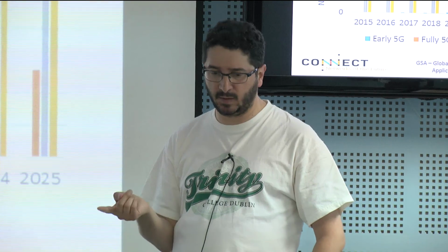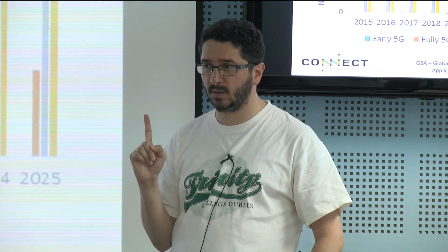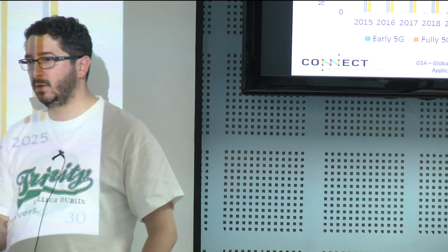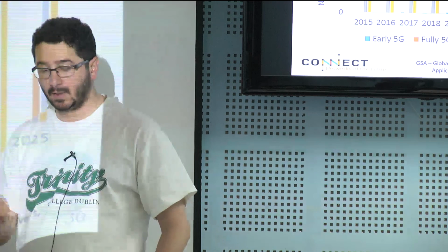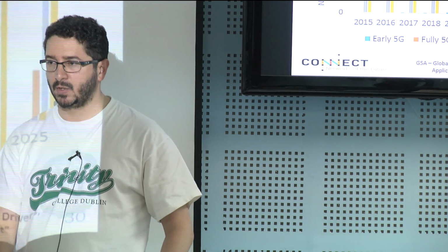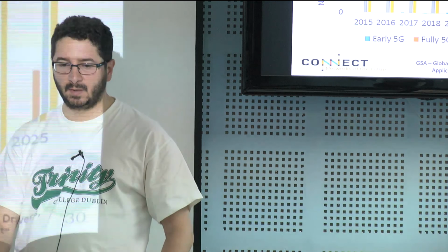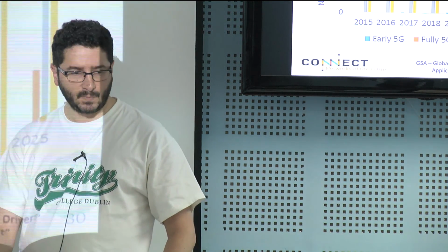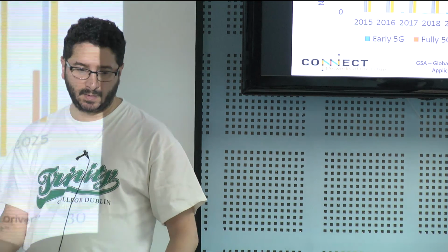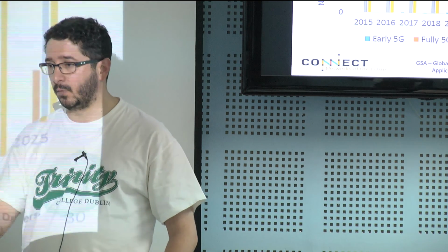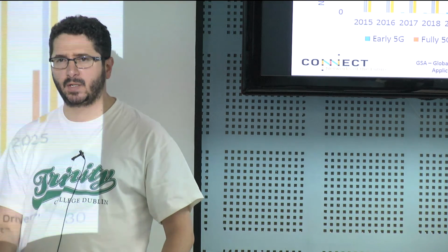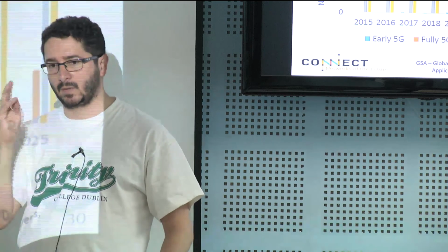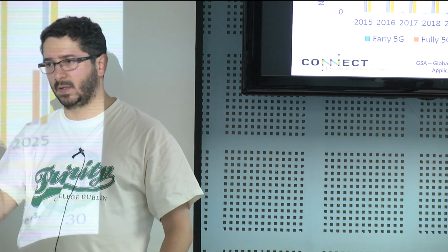There is activity going on in 3.5 gigahertz in the US, which is mostly used for radars, especially naval radars. The Federal Communications Commission, FCC, suggested this to be used in coexistence with small cells. Integration with Wi-Fi is relevant, of course, at 2.4 and 5 gigahertz. There are a few radar bands in the sub-6 gigahertz range. For millimeter wave, normally they consider 28 to 31 and 60 gigahertz.